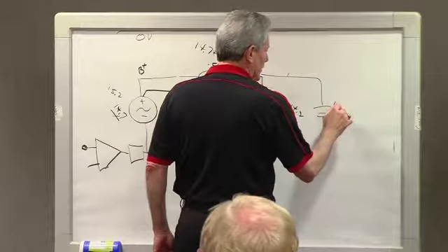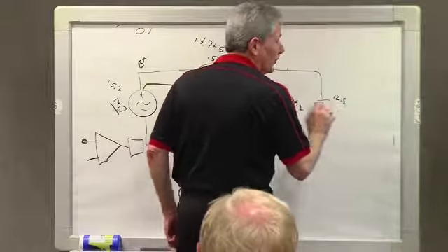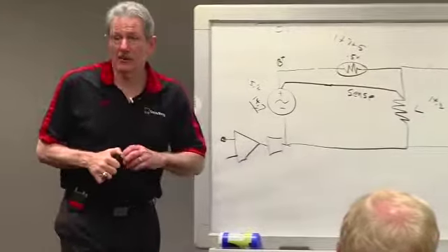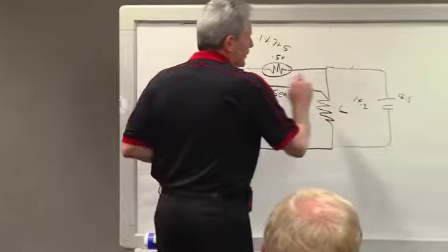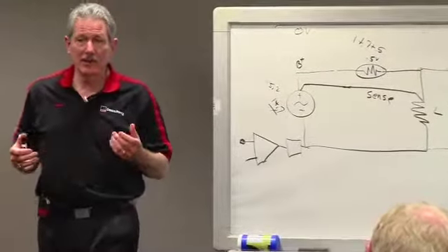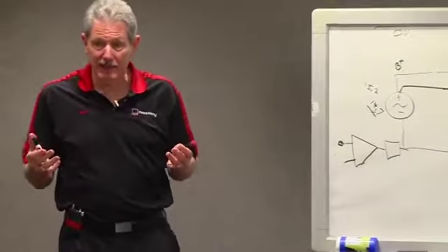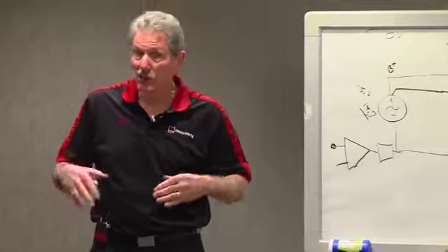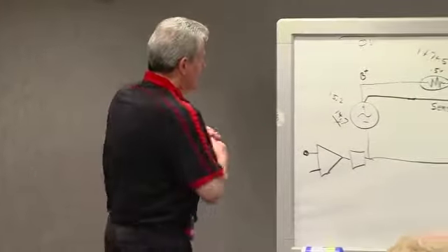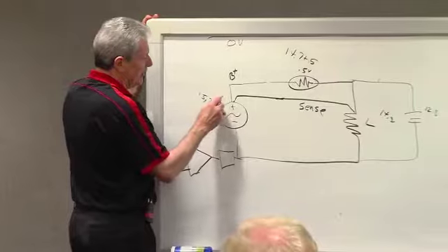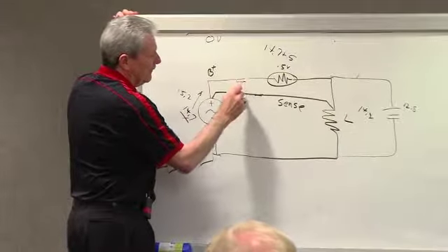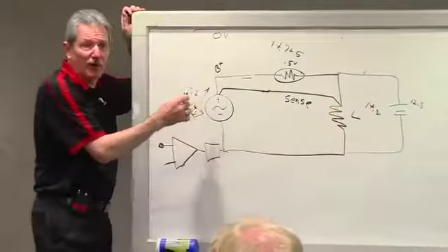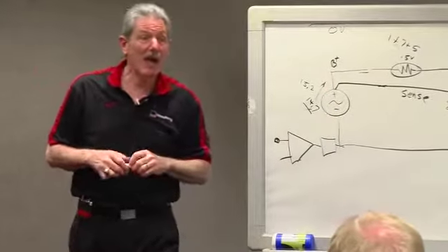This is 12.8, which is the open circuit voltage. So if I'm not charging it, this voltage here will drop to 12.8. When it drops to 12.8, the regulator says, I'm below set point, so charge. So the voltage here begins to increase. Well, since there's no way for this to get pulled up, this voltage will continue without bound.